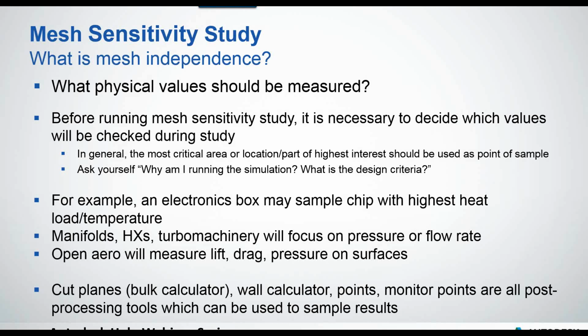Heat exchangers, and a lot of these things are going to be pressure, usually not velocity, but that's what I would focus on anyway. And how do you measure these? I use bulk calculator with planes. That's what I did my example on. And you could use points, you could use monitor points, really there's a bunch of post-processing tools you can use there to sample results.